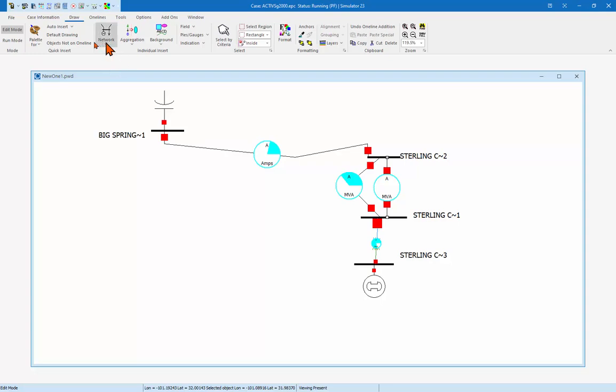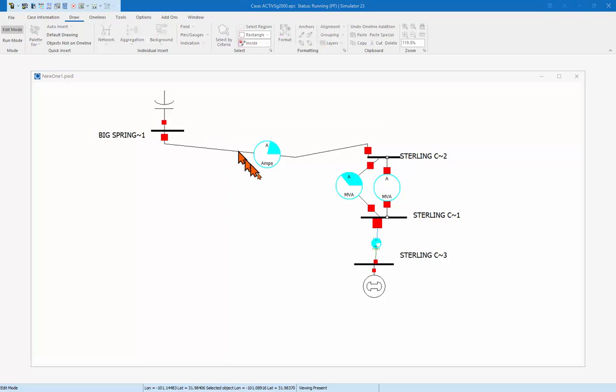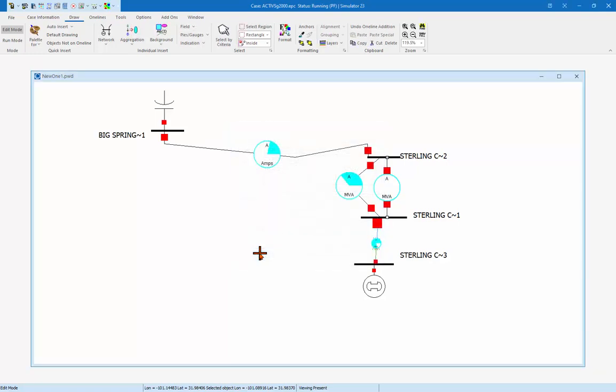This is just back here. I go to Draw, Indication, and I can choose Circuit Breaker, and I can stick one on the middle if I want. Again, it's not really a breaker. If I go over to Run Mode, I can click on those symbols and it'll open the transmission line. And any breaker symbols that occur on a transmission line or transformer just have the effect of opening or closing the entire line. It's not a breaker as you would think of in an operational sense.